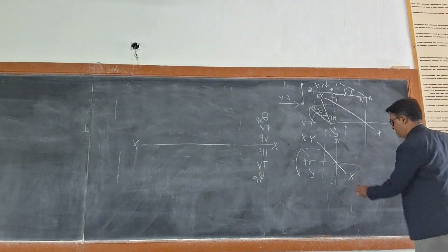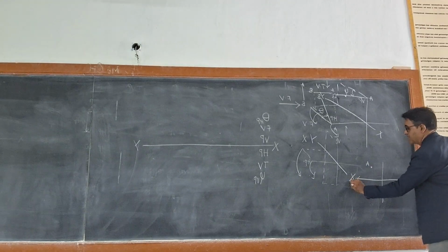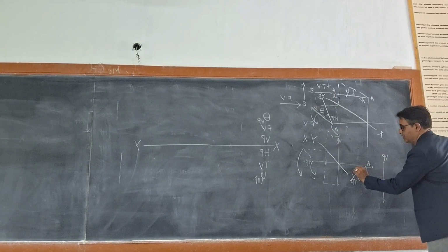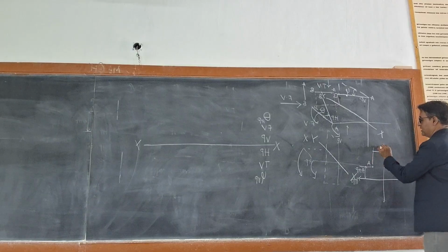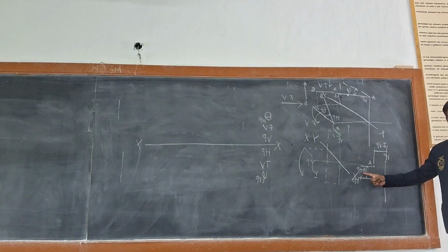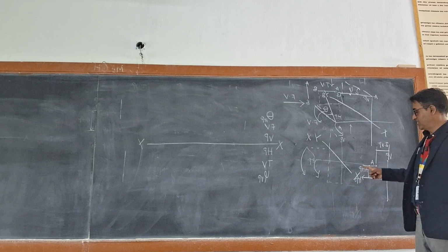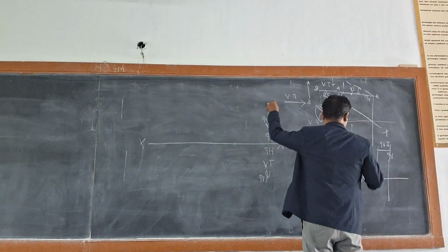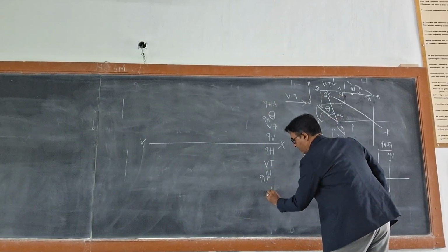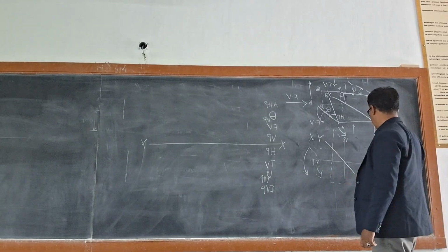Next, say this is my point A and this is HP and this is VP. This point A will be having a distance, I call it as above HP, and this is called as in front of VP. If I want to visualize this above HP distance, the logic here is you have to look from the front. Therefore, front view, where is front view? Above XY. Therefore, the above HP distance will be above XY and the in front of VP distance will be plotted below XY. So this is the basic thing.